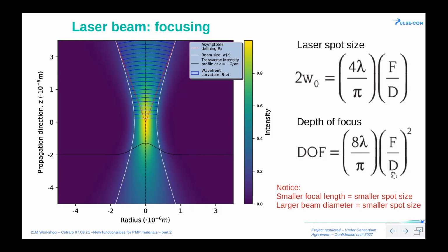If we have a high enough depth of focus, the laser processing is not going to be sensitive to the flatness of the target. However, if we use, for example, a microscope objective with 100 times magnification, and the flatness of the target changes by, let's say, 2 microns, it's going to go out of focus. This is very important when we're trying to do high resolution laser processing.